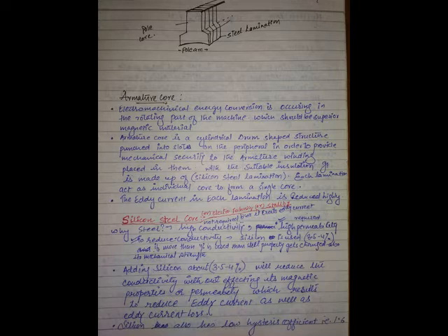So what happens in the coils inside? They will get damaged. So the collection of current from the commutator through the brush should be as sparkless as possible. For that, you need to offer good mechanical conditions and good electrical conditions. Discuss. Keep the heading: brushes.